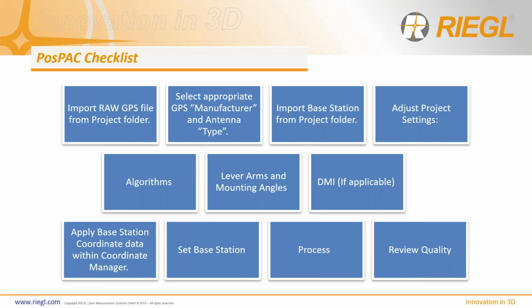The DMI is the same way. You need to have as precise a measurement as possible, but you also have to allow the lever arms to float a little bit as your vehicle is on suspension typically. Obviously, high rail vehicles are a little bit different in their suspension as you're more or less fixed to a solid wheel as opposed to the tires that are going to change as they heat up.